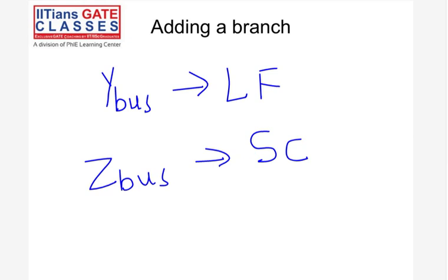So now we are going to build a Z bus. We take whatever grid network is given to us, and build it from scratch. First we decide the reference bus. If we have a shunt, we always prefer to take ground as the reference bus, right? And then we take the first bus. We take whatever has a shunt connection to the ground, and this value would be Z01.